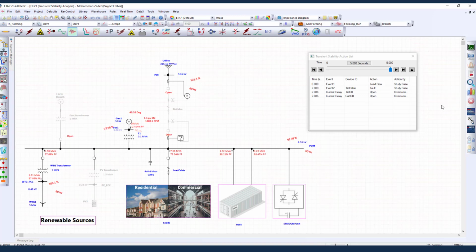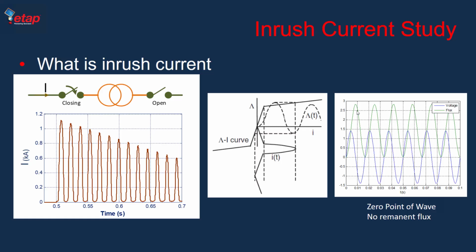Again, here we use a generic model for our inverter, but this model has better capabilities in terms of modeling the true capabilities of grid forming and following. And this is more useful for early stages of projects, where the vendor is not picked or the model is not available, and we want to use something for the design of the system.